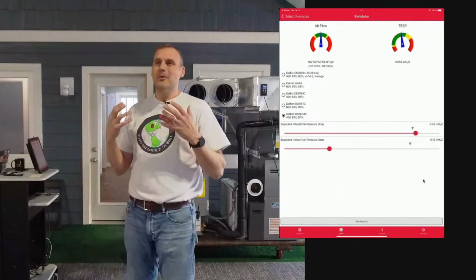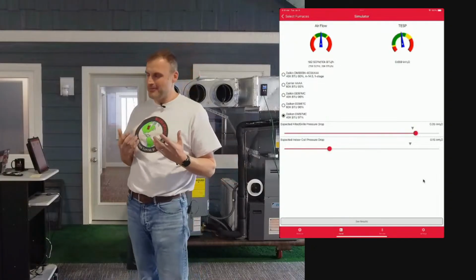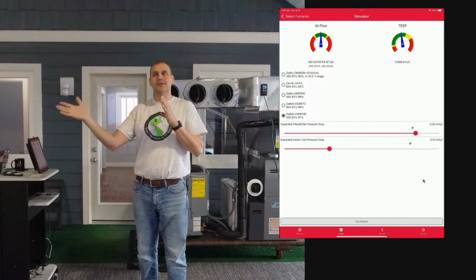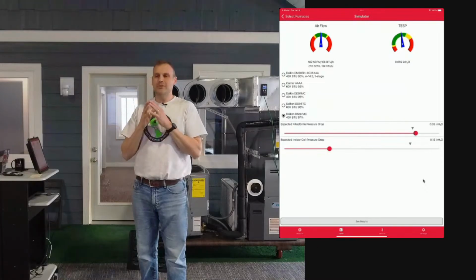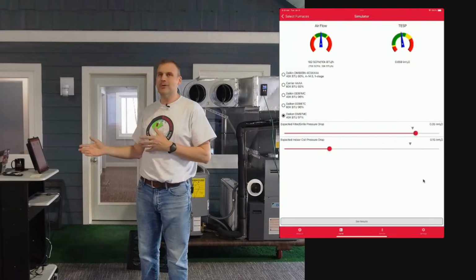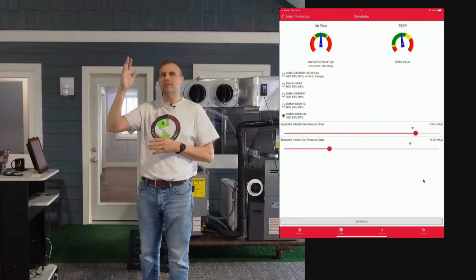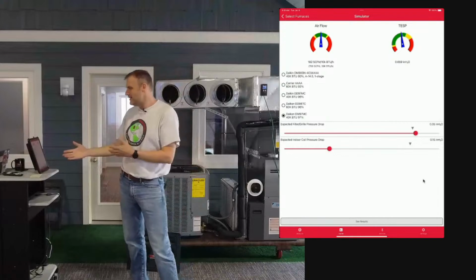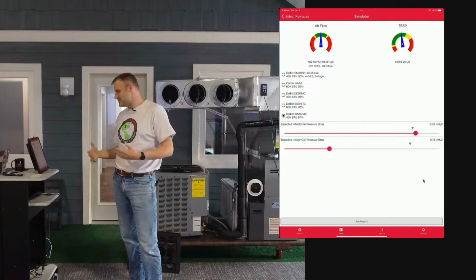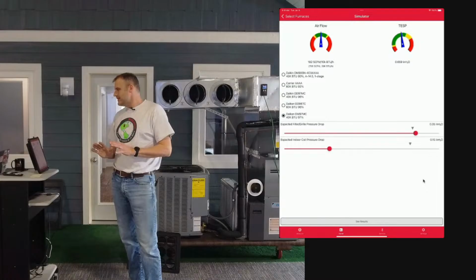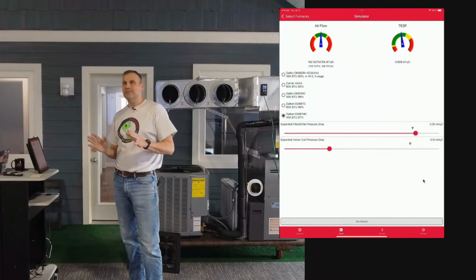Okay, what am I trying to showcase for you right now? That total external static pressure dial where the green, yellow, and red land: when you change the TESP target that we've been talking about through the workflow, you will change where those colors land based on the input data. So that will happen inside the app. Sorry, should have baked in a furnace that had a lower TESP. I showed you that. Okay, so that's how we're handling forecasting for furnaces. Choose and use instead of design and find.